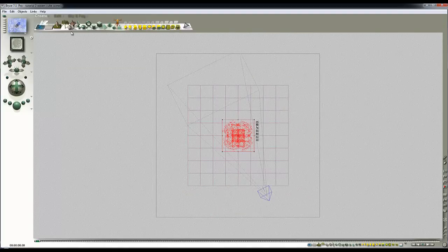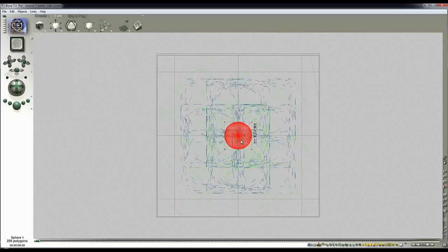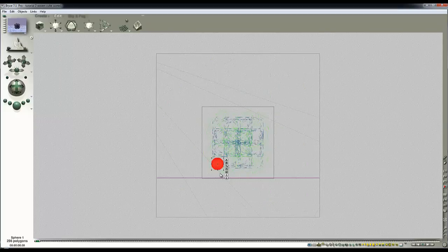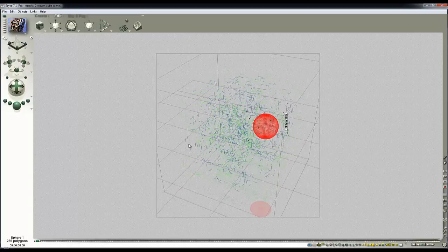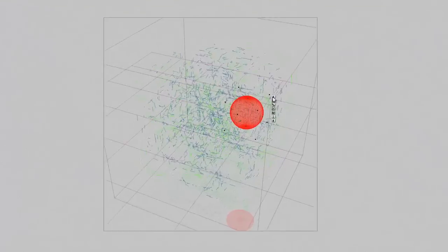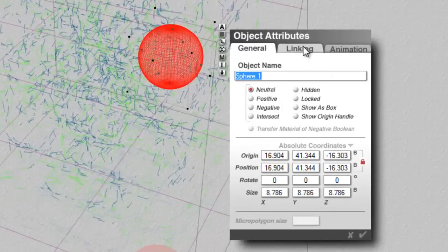We'll create a target object. So I've just created a sphere. I'll shrink it down. That allows me to position the focus of the depth of field very accurately on the model. So if I put it on this top corner by switching views, I'm using the 1, 2, 3 keys as a shortcut to shift the camera views. One is the perspective camera view. This object can be made invisible in the render by just selecting hidden. We can call it